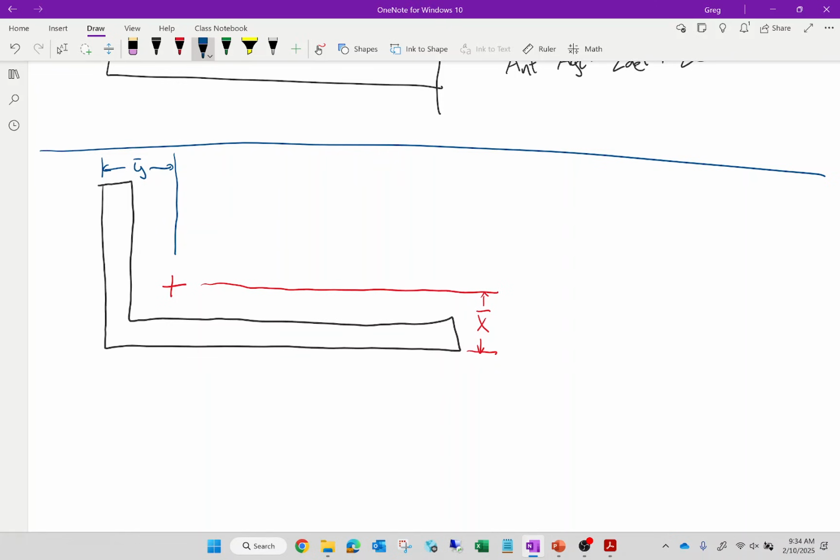That's it. All Mohr's circle is, is a transformation of stress as you take your cut at an angle instead of cutting up and down. What Mohr's circle is trying to figure out is what's the worst way of cutting it to get the highest stresses, because that's how it's going to fail. That's Mohr's circle, everybody, at a high level. I'm dead serious. That's all there is to it.